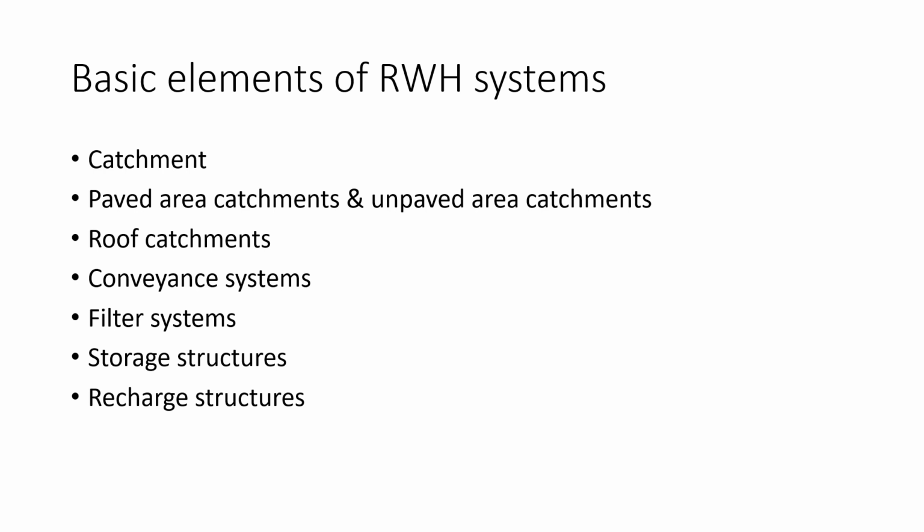But very important, a carefully designed and constructed conveyance system can divert more than 90% of all the water that falls onto the roof. And accordingly, we have to use different mechanisms for flat roof conveyance and for sloping roof conveyance systems.